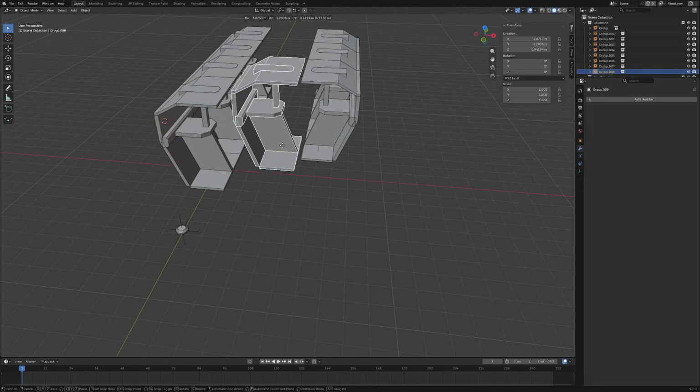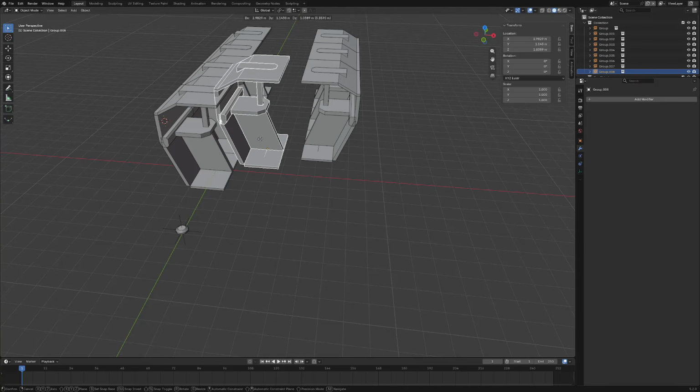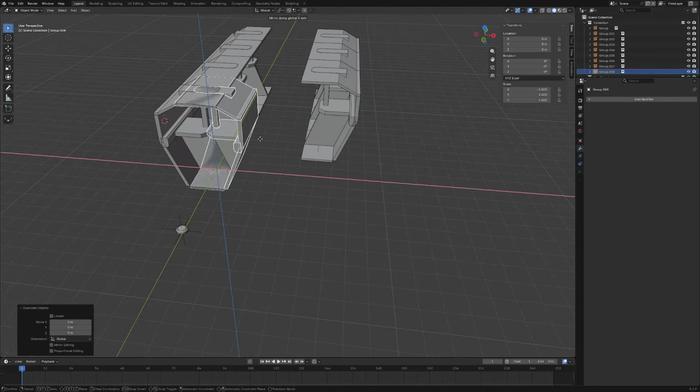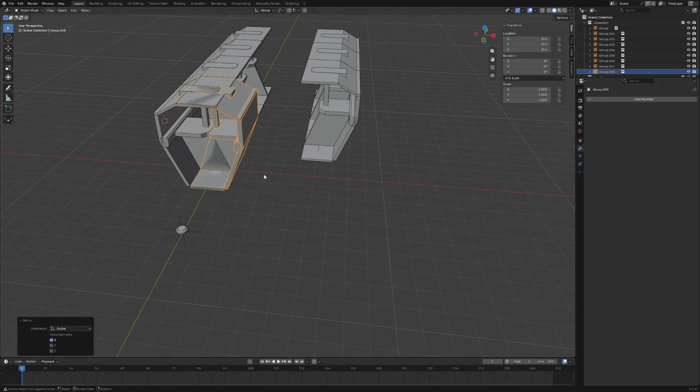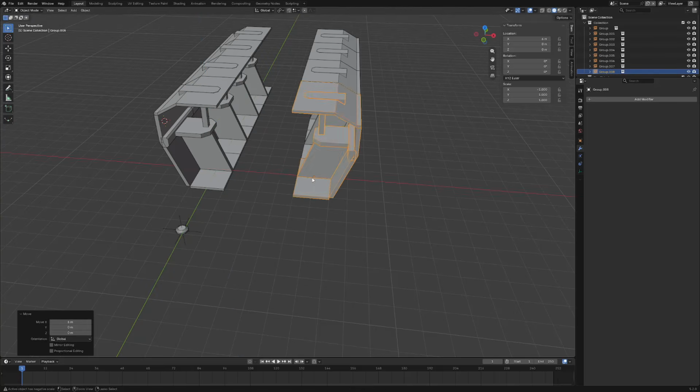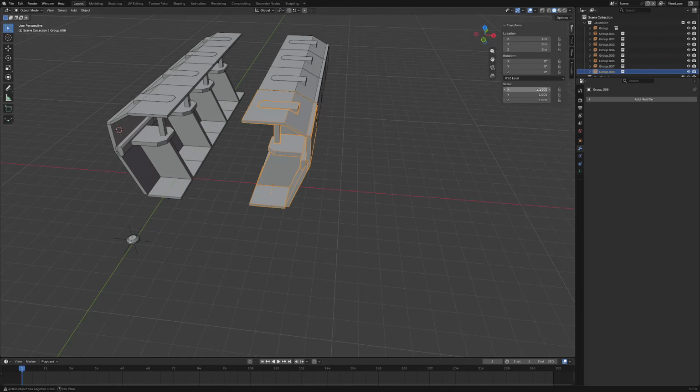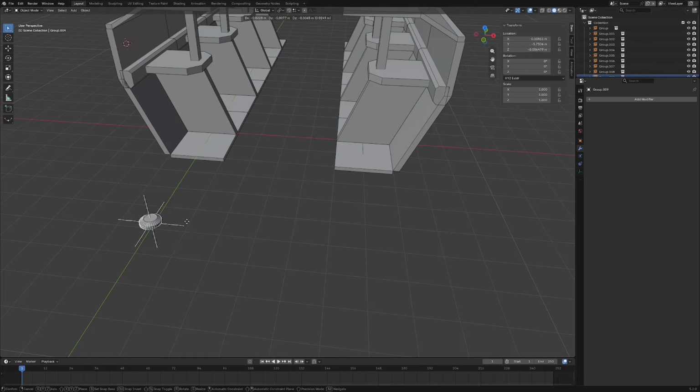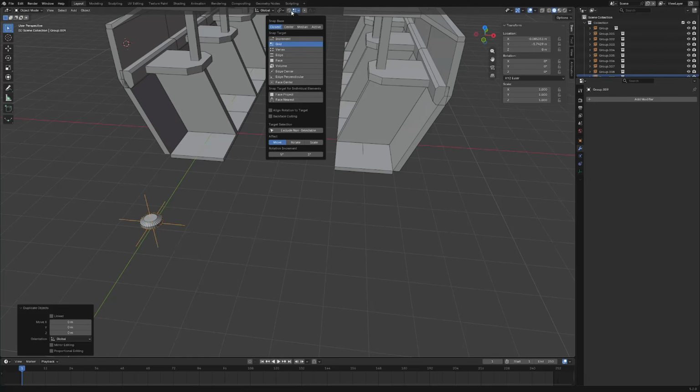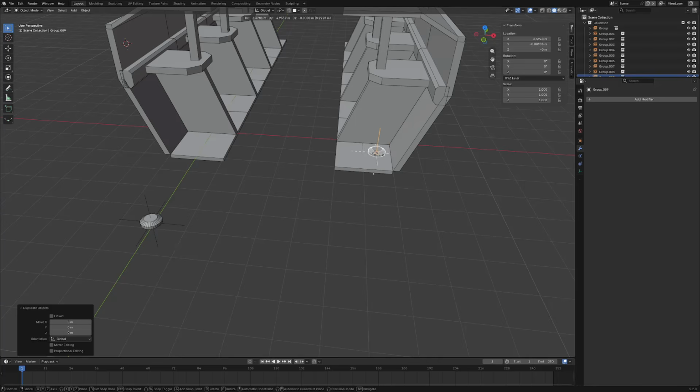Okay, so if I hit Shift D and duplicate this and right click, Control M, middle mouse click, or XYZ, I can flip this over. Right? And so if this is flipped over here, you can see it inverts the scale. Okay. So if I took an object like this and I Shift D and duplicate it, and I want to snap to the face, align rotation to target, and use center again, and I hold Control.